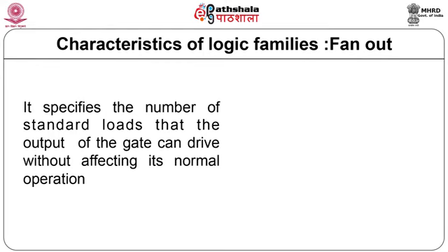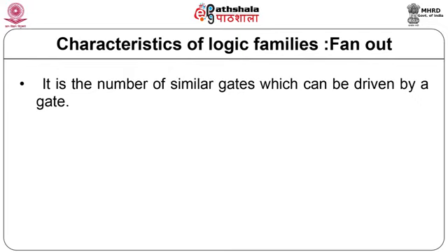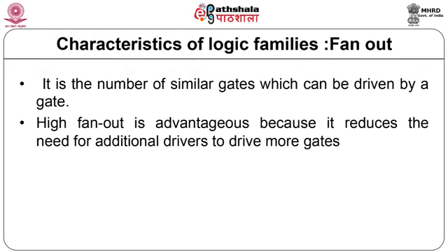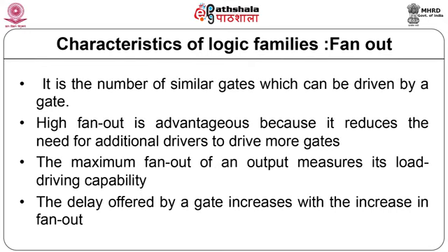Next characteristic of logic family is fan-out. It specifies the number of standard gates or loads that the output of the gate can drive without affecting its normal operation. It is the number of similar gates which can be driven by a gate. High fan-out is advantageous because it reduces the need for additional drivers to drive more gates. The maximum fan-out of an output measures its load driving capability. The delay offered by a gate increases with the increase in fan-out.